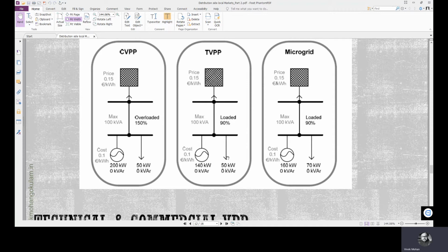As we have seen in virtual power plant, the local load is transacting only with the retailer. So the operator may not be directly communicating with the load that there is a problem with the line carrying capacity. The constraint is already hit, so you have to adjust your load demand, but flexible demands are not that encouraged in virtual power plants because it has no direct connection with the operator.